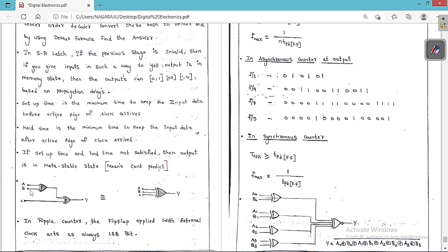So you can say clearly this is called an XOR gate and this is also an XOR gate. So what is this combination? This combination is nothing but a simple XOR gate with 3 input gates. I already told you, the XOR gate is going to satisfy the associative property. So instead of like this, we can make it a combination of 3. So like this, we can keep this one.